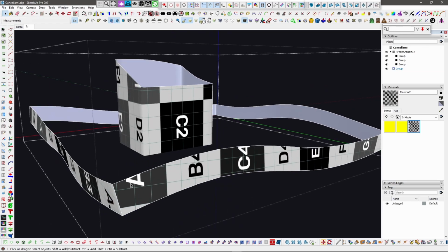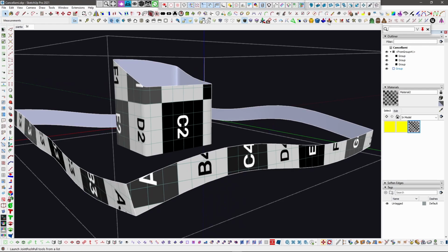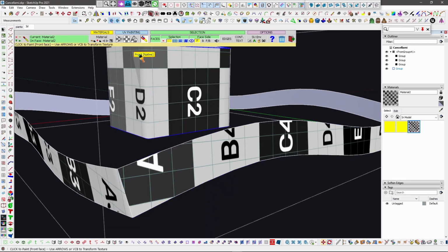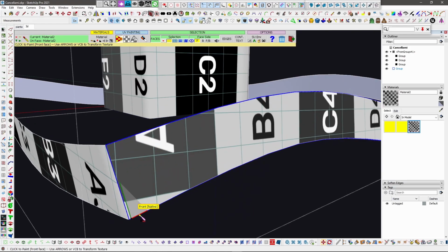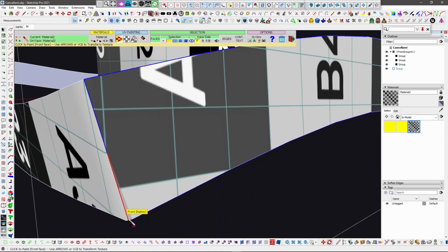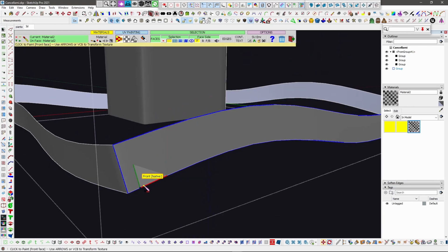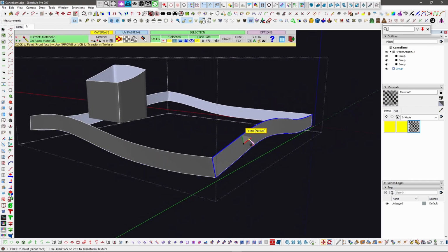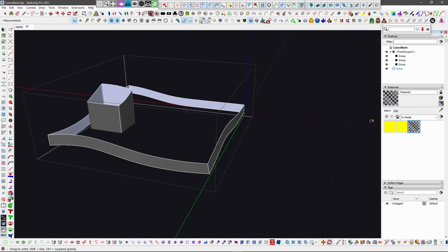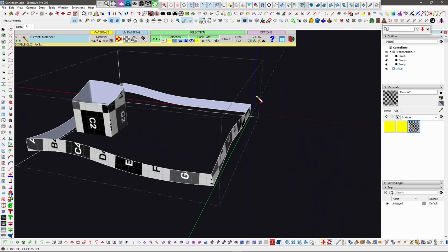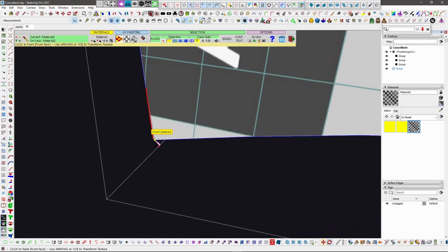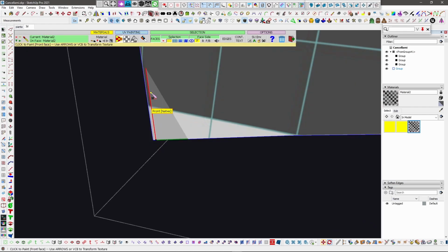But before I do this, I want to use this trick to straighten my UV island. I use True Paint. This is the fastest way to get a flat strip in this kind of unwrap. So you want to make sure you are in surface mode, because I marked my UV island with surfaces, I'm pretty sure I will do a decent job with the surface mode and quad mode for mapping.